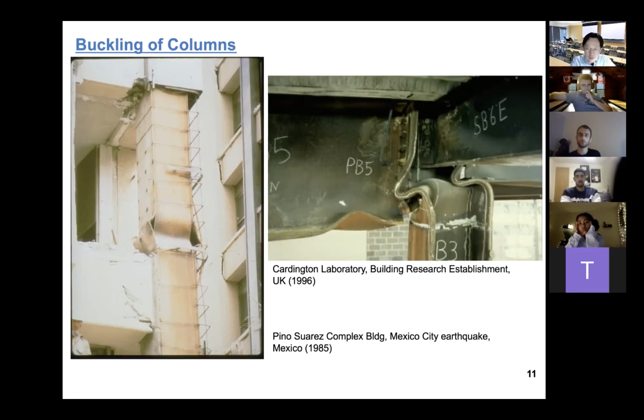And that means whatever we have used so far, you can only use it to analyze the global buckling, not the local buckling. That's the limitation of the buckling theory that we use so far. However, when we move to beam-column buckling, we can study local buckling. So this classical column theory only applies to global buckling. You can calculate the buckling load, but you don't know how the cross-section is going to buckle. Why? Because you have different kinds of cross-sections, even though they all share the same value of moment of inertia.